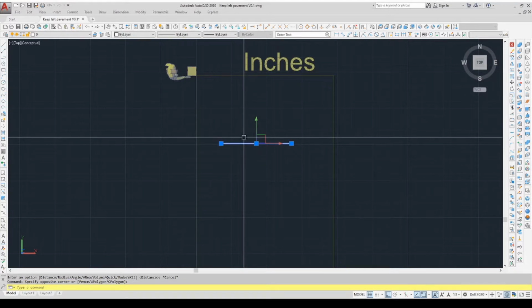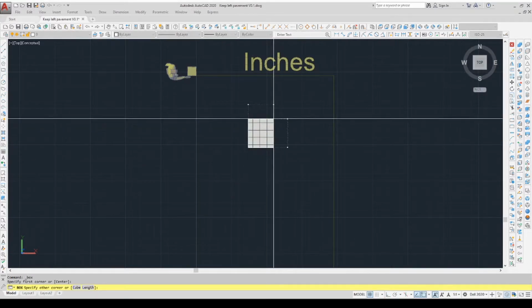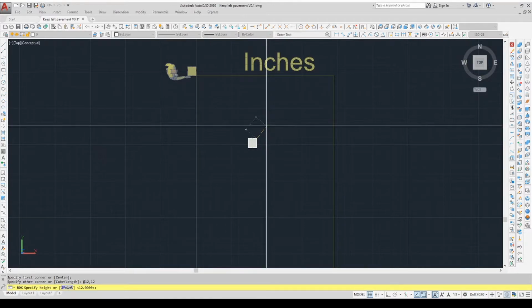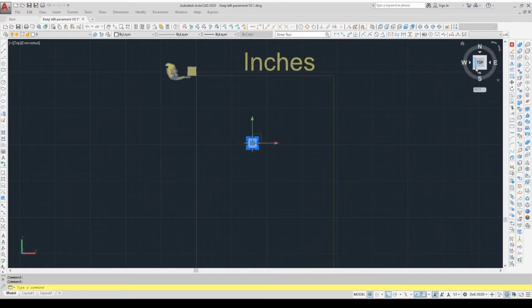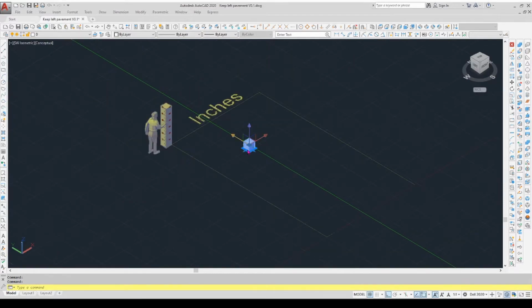It's a similar thing to what you saw with a block. Just delete that. If I insert a block, I can again dimension that 12 by 12 using the comma in between. And it's now asking, you've drawn the base, but how high is it? So I type in 12 again, and it has made a block. Now if we turn it onto isometric view, you can see my little 12-inch block again.